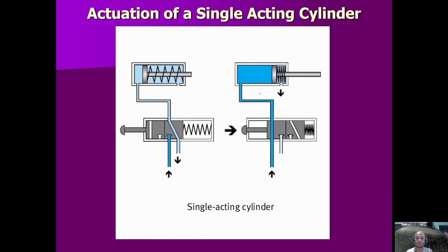While we also have double, okay, this one. If this is your valve, this is a push button with spring return, and then this is a 3/2-way valve. The flow here is closed in its normal position, but if you push the push button, this one will go to this one. So there will be opening of the valve, and the flow will go here to here, pushing the piston to the right.